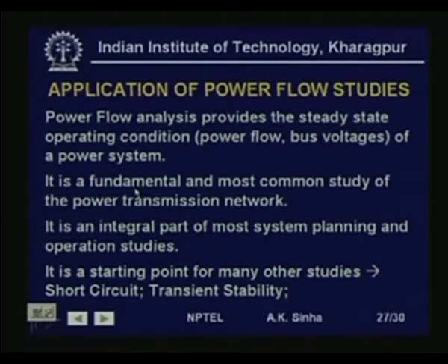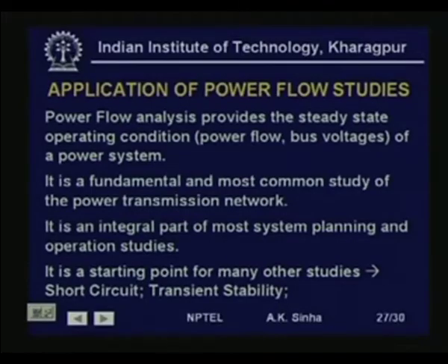Now, it is a fundamental and most common study for the power transmission network. That is, the power flow study is one of the most common studies done in power system analysis. In fact, as we will show you, it is an integral part of most system planning and operating studies. All system planning and operating studies depend on load flow analysis. And that is the reason why we have all the time been emphasizing that we need very efficient algorithms for solving power flow for large systems, because we need to do hundreds and thousands of load flows for planning and operating studies.